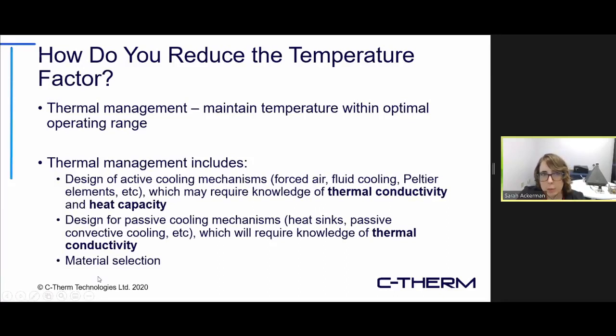So thermal management is basically an umbrella term that includes a wide variety of strategies, but you can really break it down into two main areas. The first one is the design of active cooling mechanisms, such as forced air, cooling fluids and heat exchangers, Peltier elements, basically anything where you've designed a device specifically to pull heat away from where it's being generated.